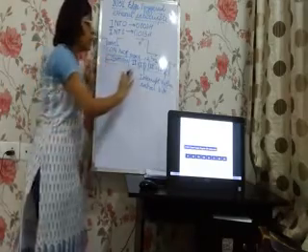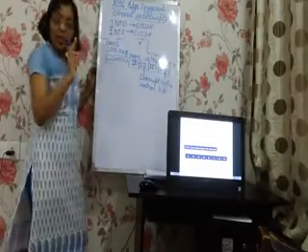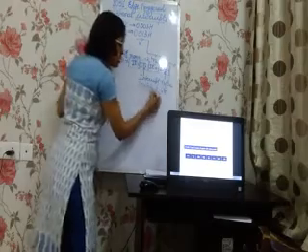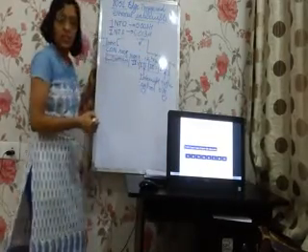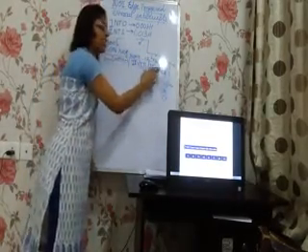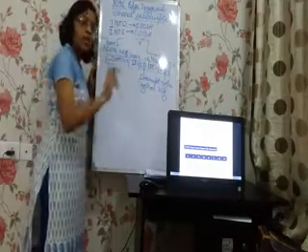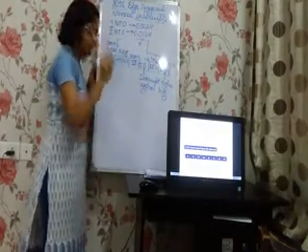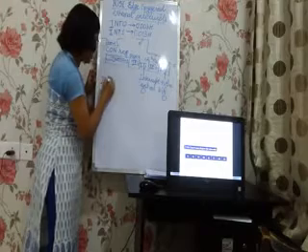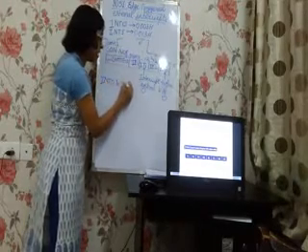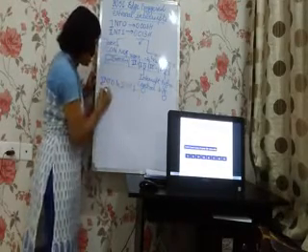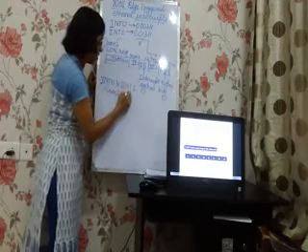Now upon reset, both these bits have logic 0 in them. If IT1 and IT0 are at logic 0, it means the two interrupts INT0 and INT1 are defined as level triggered interrupts.